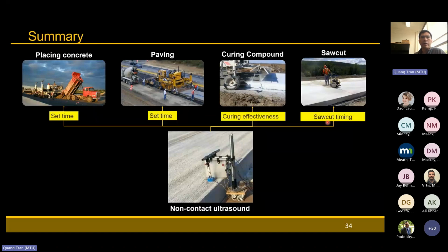One study that I don't show here is that we can use the mirror if you are interested in the crack activation below the saw joint. You can use the algorithm that I developed for the CP Tech Center, where we use the mirror to verify whether the cracks below the saw joint have developed or not, right? So we already built an environment to determine the set times, predict saw cutting, and also verify the saw cutting.